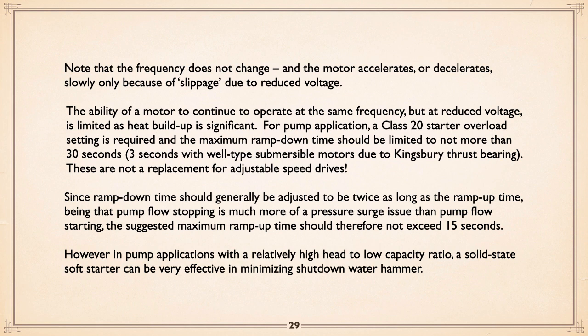using a solid-state starter, you want a class 20 overload, because a class 10 with that drawn out voltage effect, the currents, although they're not as high as you would across the line, they're there and they last longer. So you want a class 20 overload. And ramp down time should be limited to about 30 seconds, simply because you are heating the motor. That motor for 30 seconds is seeing a reduced from across the line to a lower and lower voltage, therefore it tends to heat. Now, if you're using submersibles, the ramp down time should be 3 seconds, and we'll get to that later. Not because of electrical, but because of mechanical things.